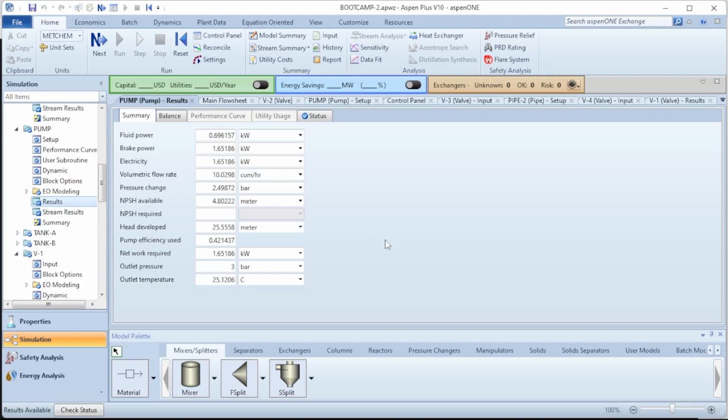So what you can do to see if cavitation can occur, you are doing this one for you to compare it with real world work. You know, every pump has an NPSH required. So when you simulate it with this, you can tell your boss, the NPSH available that will be within our piping system is 4.8.